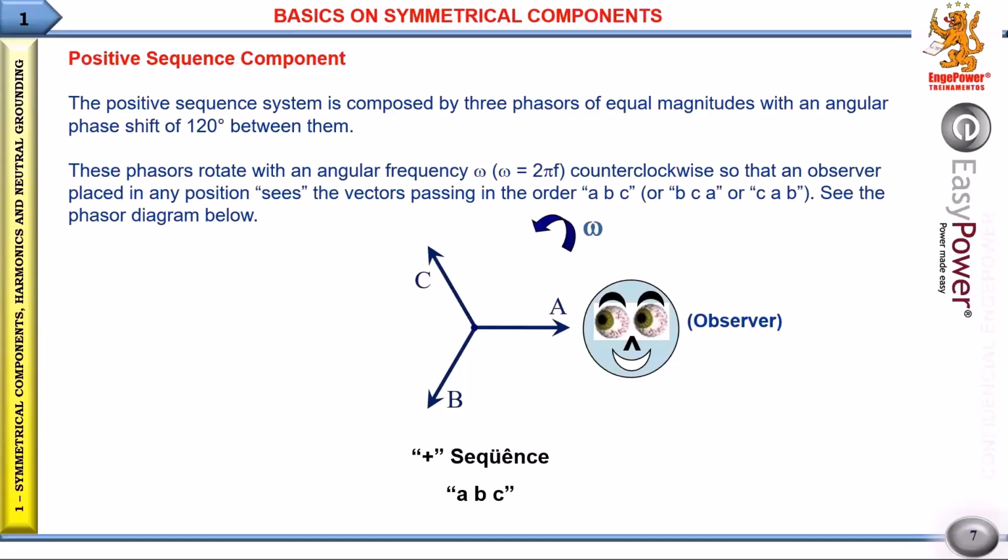He had also the concept of phase sequence. He also adopted a direction of rotation as conventional, the counterclockwise. The meaning of that is if an observer is placed in the position indicated in the figure, you see the phasors rotating in a phase sequence ABC.